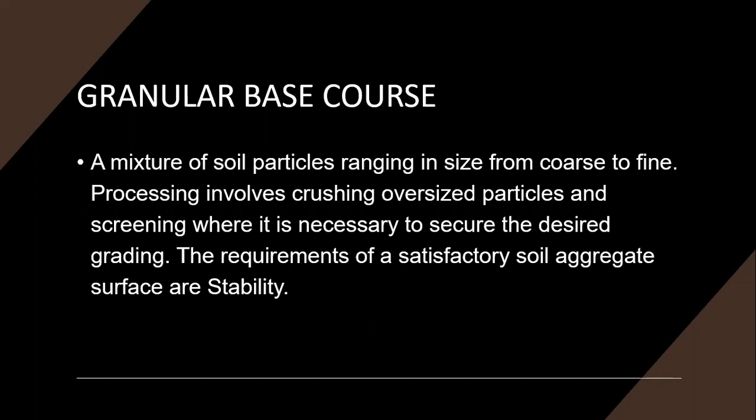The granular base course consists of a crushed gravel or graded crushed gravel, which has a maximum particle size of only about 20 mm to 40 mm, as I did my research, and then it is separated from the subgrade by a granular subbase course. However, the granular subbase course consists of a maximum particle size of 80 mm to 125 mm.